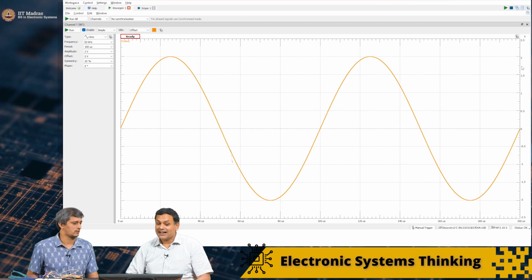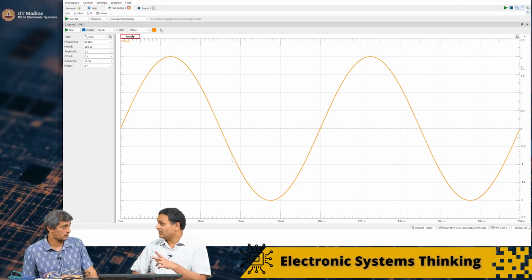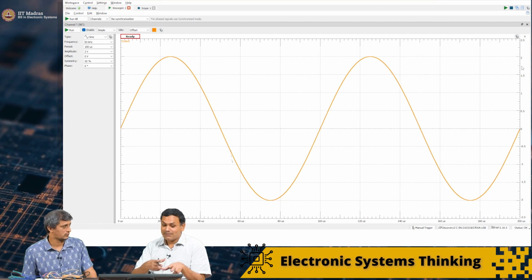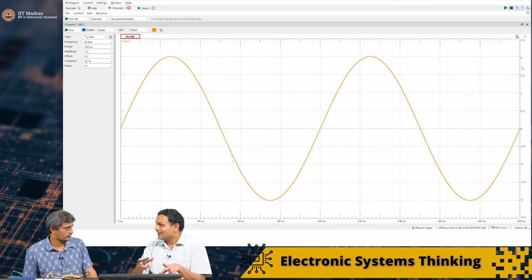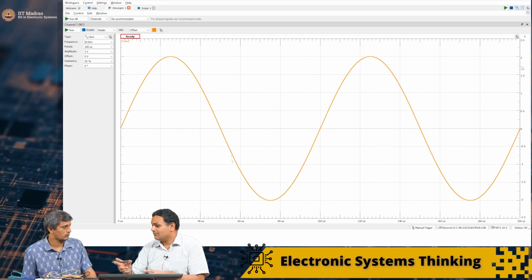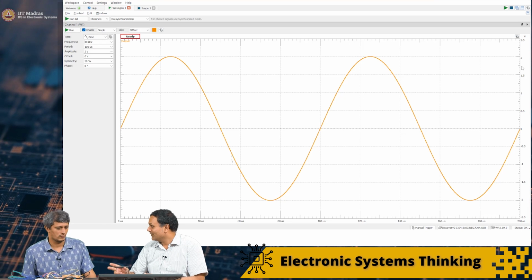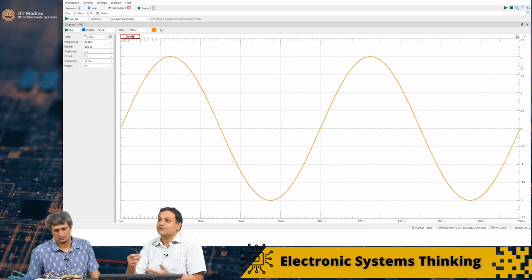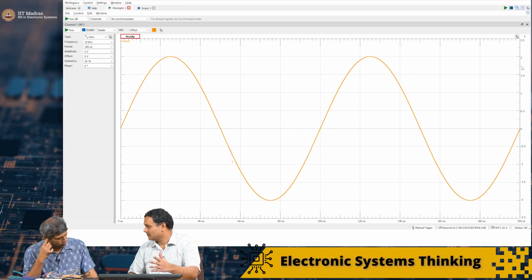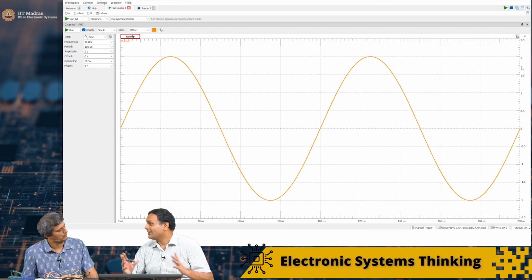By the way, I also want to tell people, you are now radiating outside in free space. There may be somebody using this 10 kilohertz, whatever we are experimenting. You have to be careful. Don't make your antenna too efficient, because you will interfere with others. Don't use a commercial antenna, and don't use amplitudes too large, because you will indeed interfere with whoever is using it.